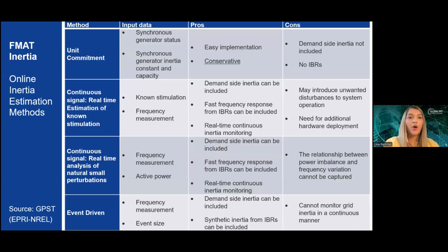Now, talking about online inertia estimation methods. As I mentioned in the beginning, in G-PST we are considering new ways of tracking inertia in real time. Currently we have an open source tool that uses the unit commitment. We are tracking the H of all the synchronous generators in the system and providing a display in the control room for that.